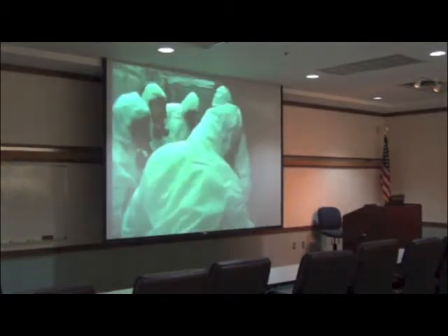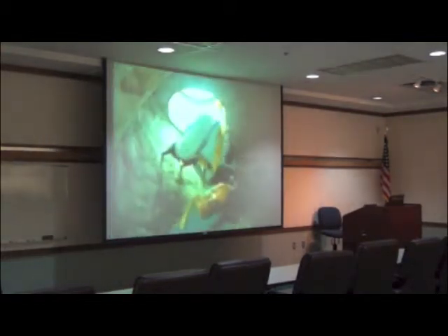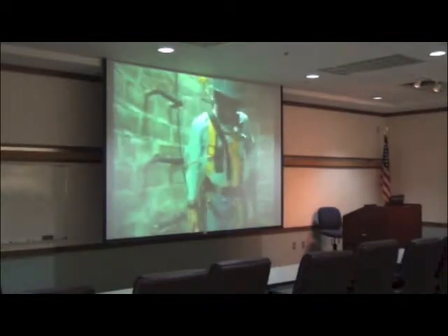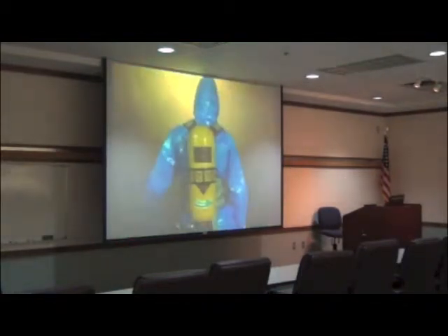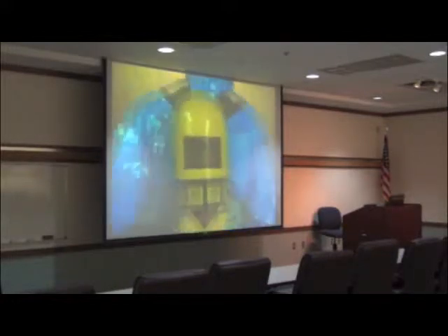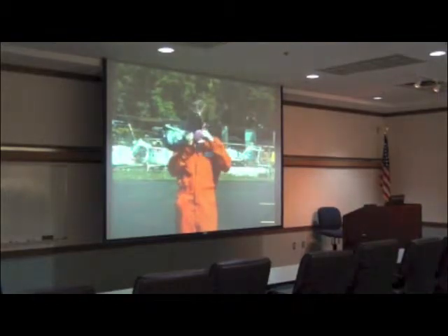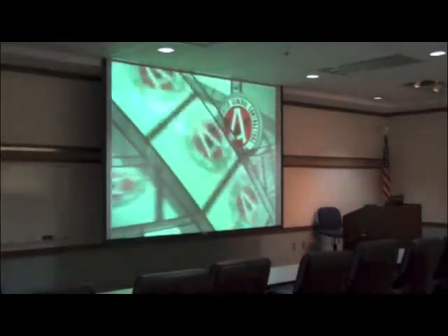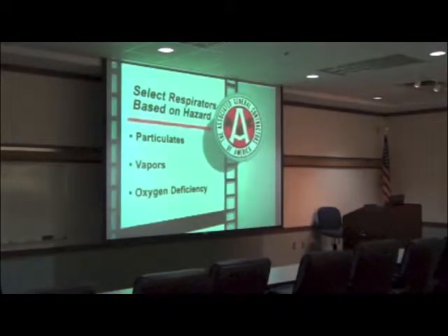There are three main types of respirators: supplied air respirators, which provide pressurized breathing air; self-contained units that have air in a tank that you carry on your back; and air purifying respirators that use filters to clean the air you breathe. Select respirators based on the hazard to which you will be exposed. These hazards include particulates, vapors, oxygen deficiency, or a combination of hazards.